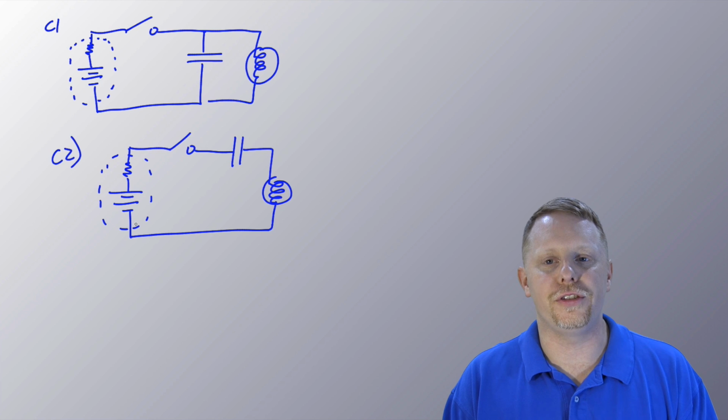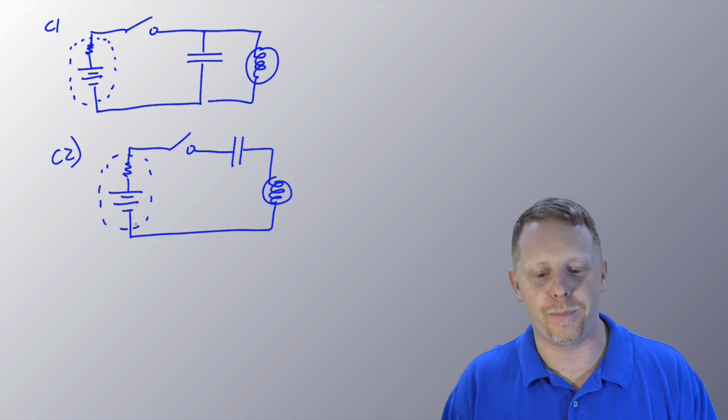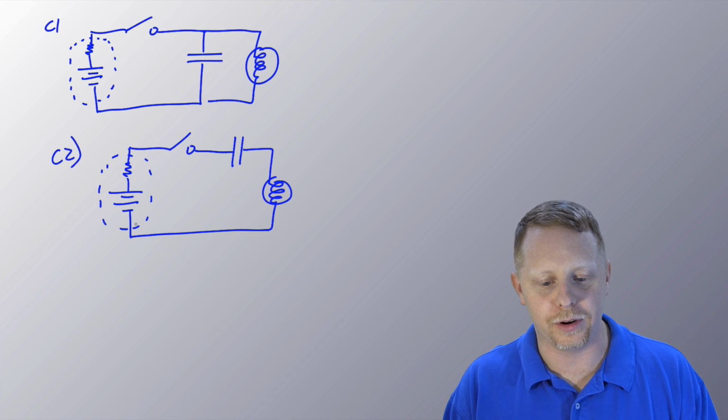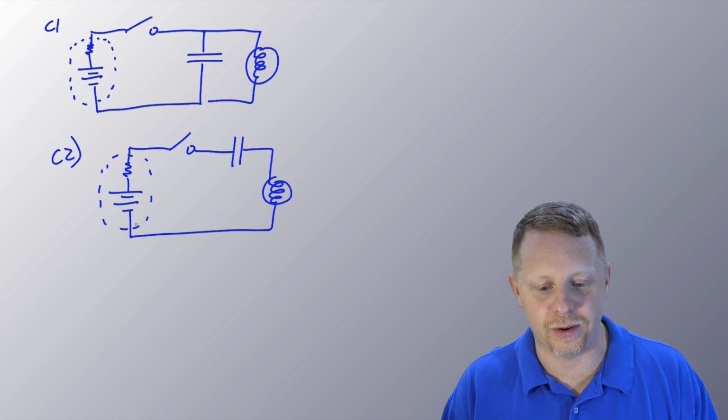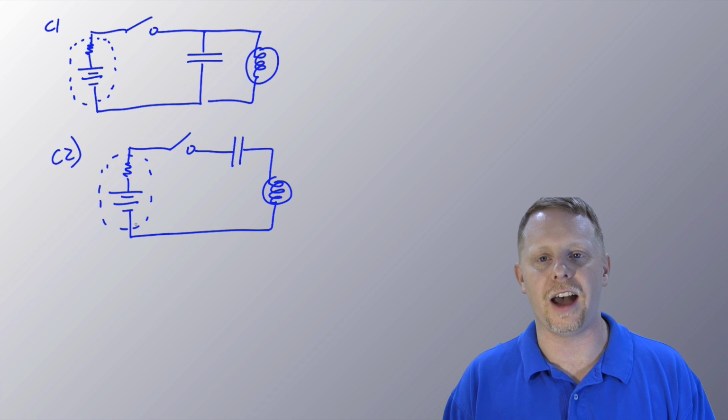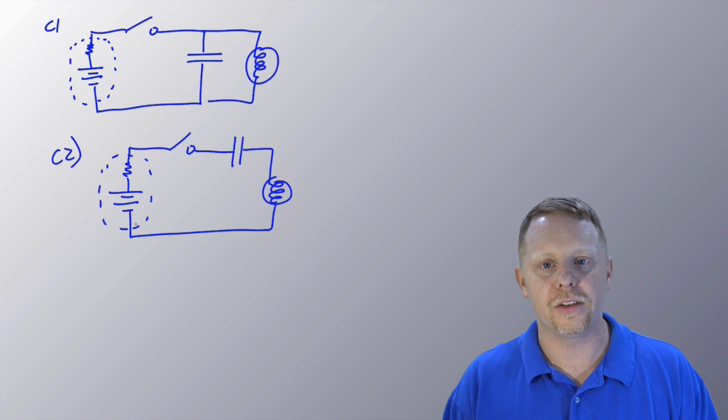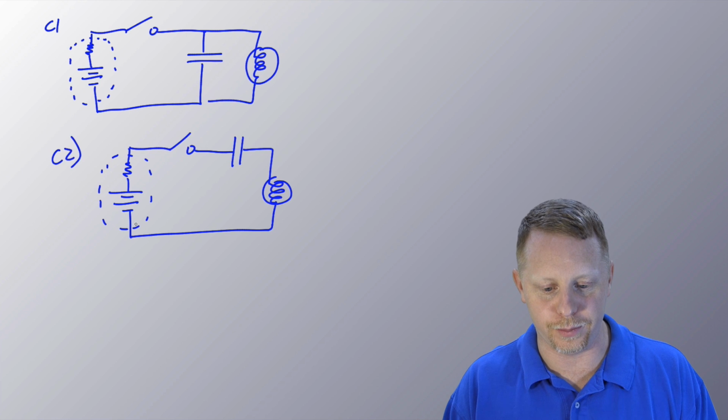When the switch is first closed, maximum current flows through the circuit as the capacitor is charged, so you've got maximum current going through the bulb. As it gets closer to its maximum charge in the capacitor, however, the current flow dwindles, eventually stopping when the capacitor is fully charged. So after a long time, there is no current through the bulb.